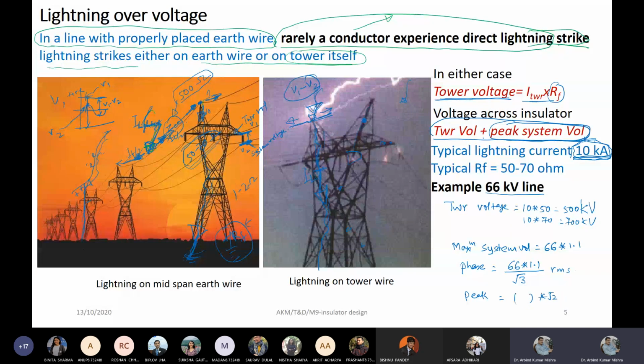Now, one thing you might have observed is that I use the words maximum and peak very consciously. When you studied in the very first year, you may have expressed Vt as Vm sin omega t, and called Vm the maximum system voltage, or maximum voltage. But now the definition for the maximum system voltage is something different.